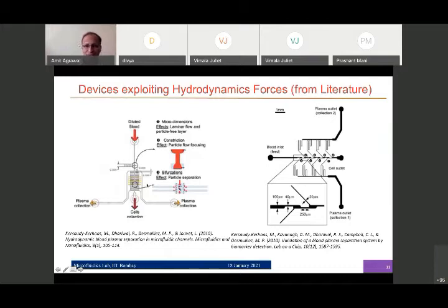So you can see that there is blood which is fed in from one side. It passes through these very intricate shapes which are given here, and the zoomed view of one of these shapes is shown further here. And then the plasma gets collected from the two sides. And in between, you can see that the blood is made to pass through these 20 micron or 40 micron size passages. And we have seen that RBC itself is 8 microns in size. So that means 3 of these cells coming together at the same time is good enough to create a blockage.